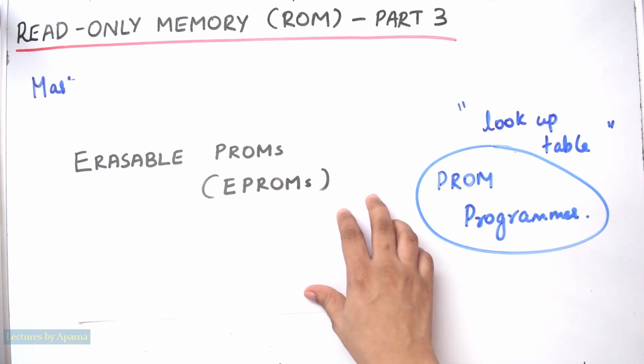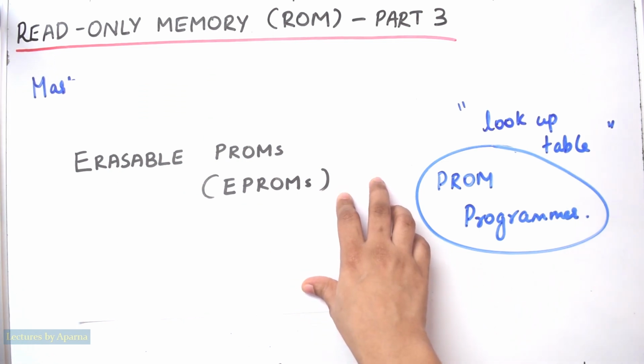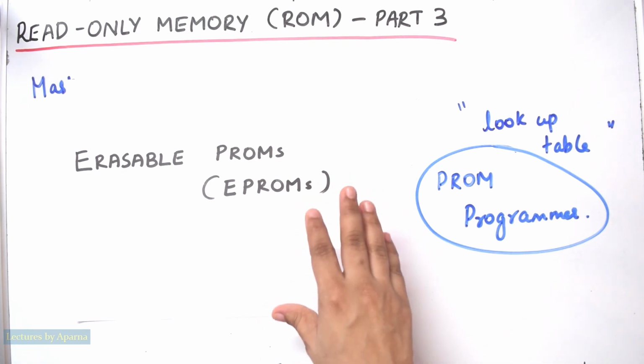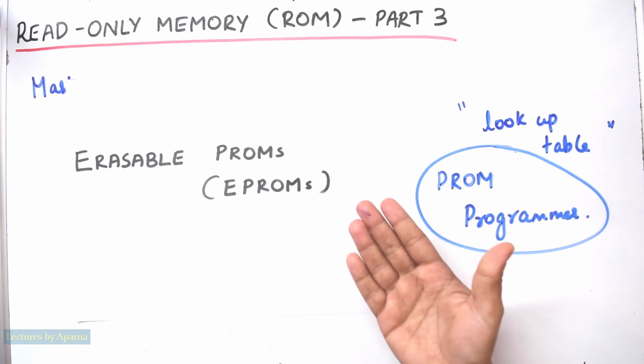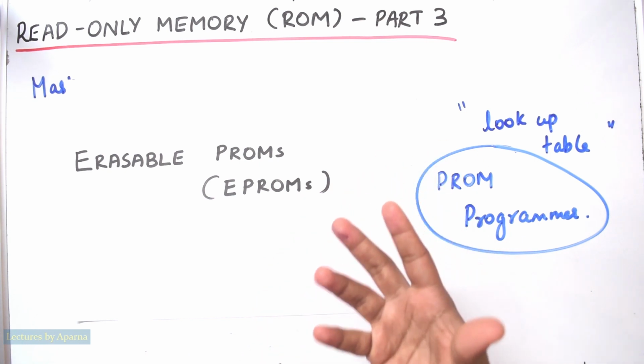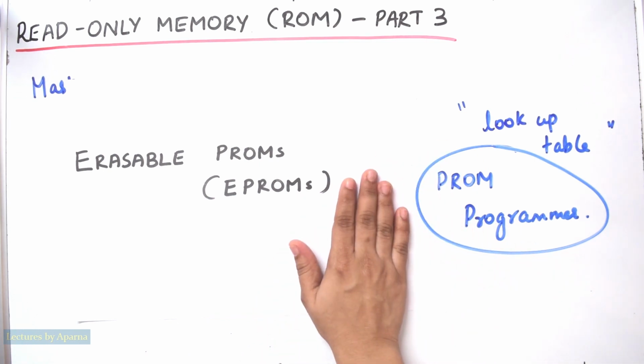EPROM is usually used in the developmental stage of a project. With EPROM, the designer can modify the contents until the stored data is perfect. When the design is finalized, the data can be burnt into PROMs or sent to an IC manufacturer who produces ROMs in large numbers.